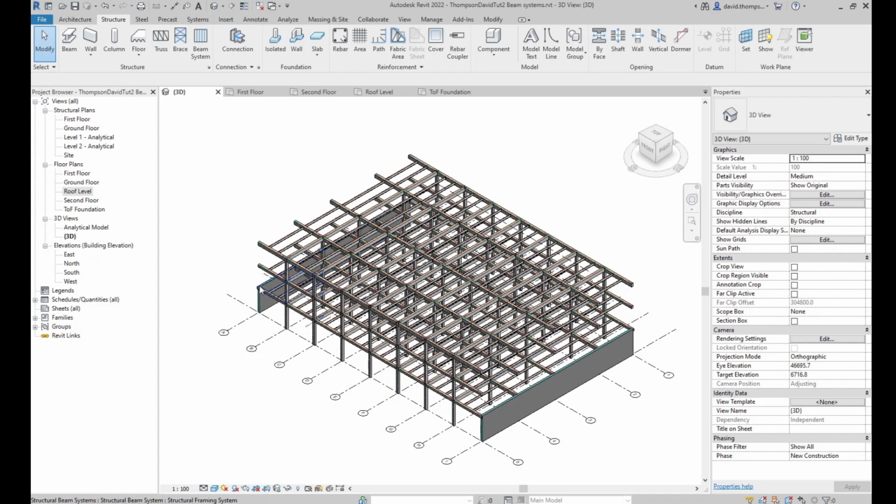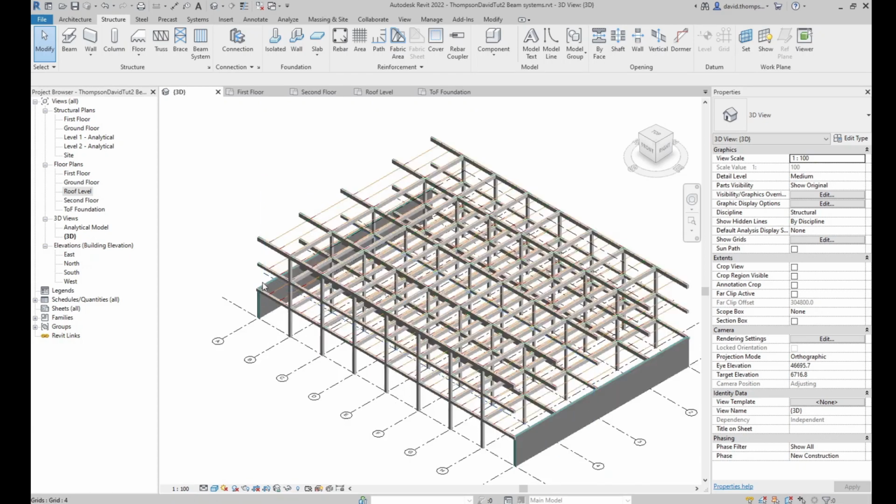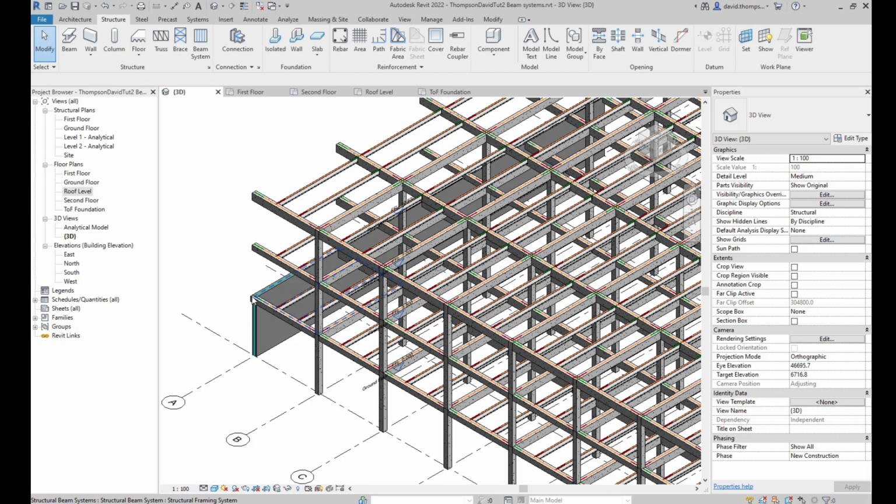So for the first floor, obviously the base constraint is going to be the first floor because we want the wall to start at the first floor, and the top constraint is going to be the second floor. And there's no offset because, again, if you have an offset of like 0.5 meters, that means the wall is going to start somewhere down here and it's going to be clashing with this wall down here. So there's going to be 0 offset when you do the wall.